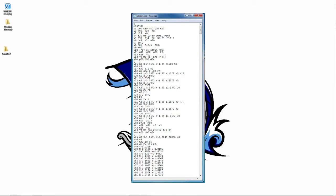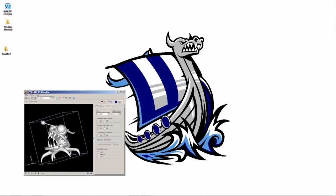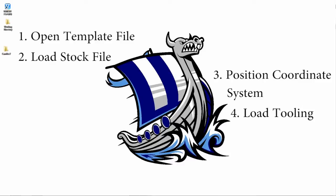Before starting Vericut, you will want to take your stock CATIA part file used to generate your NC code in CATIA and save it as a .stl file along with your .txt NC code file in your project folder. There are 5 basic steps before you can simulate your NC program. You need to open the template file, load and position the stock file, position your coordinate system, load your tooling, and load your NC program.